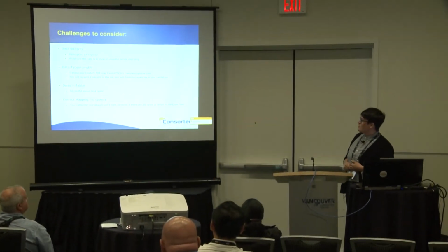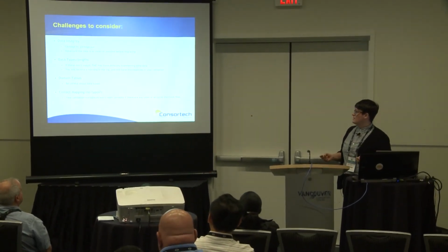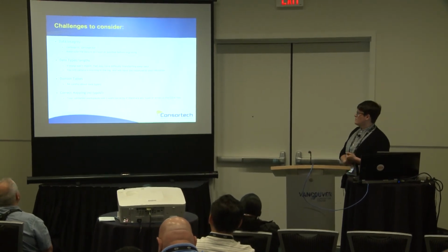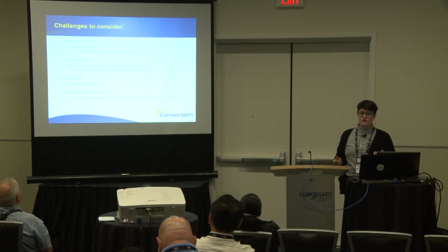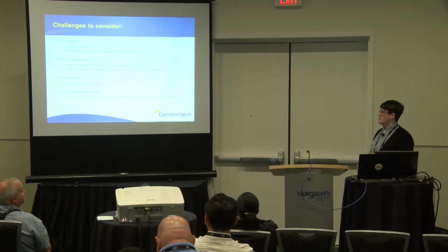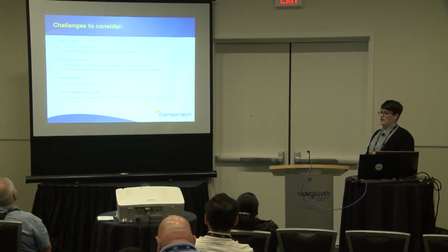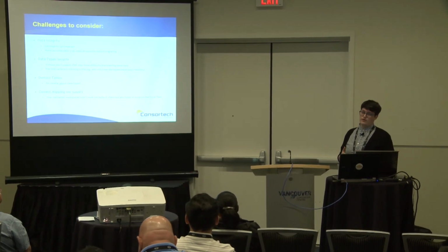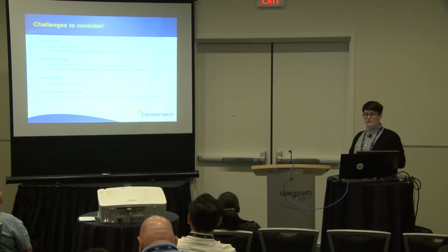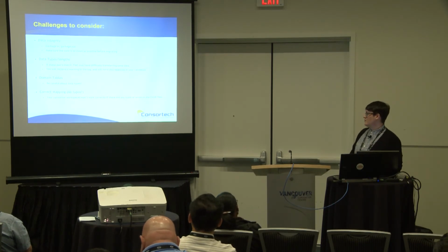So the other thing that we need to consider is the data types and the lengths of the data. So if these don't match, FME may have some difficulty transferring data. So that's another thing you need to consider. Domain tables, be careful about data types. If you have little control over any of your data, you can have some errors when you try and put the wrong data type into the right place. And also correct mapping. So make sure that when you're doing your mapping, you don't have any typos, because that can really mess up your validation, obviously.